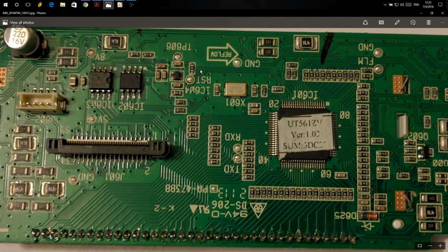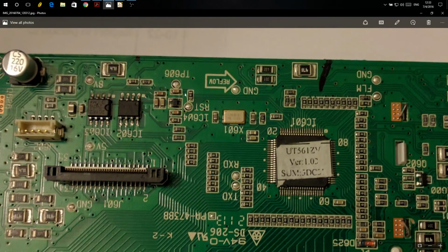That's exactly the purpose of these jumper links that they've put in here. You can just grab this with a tweezer, pull it off, and if your radio starts to work again, then you know you've got a bad supervisor IC. You'd be surprised how many receivers I saw, when I worked in consumer electronics, that actually had bad supervisor ICs. Some Onkyo receivers were quite notorious for having supervisor ICs fail in them, and the customer complaint would be dead, and it would just be a supervisor IC.